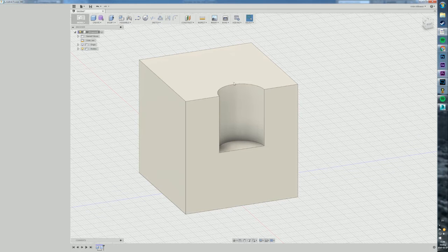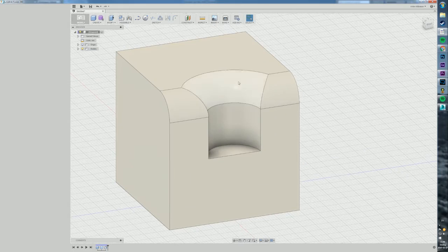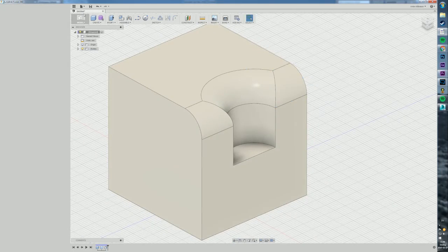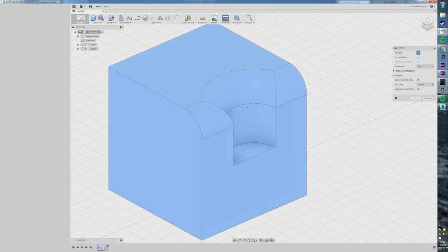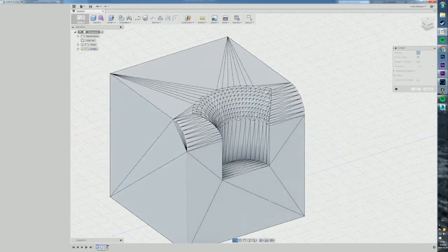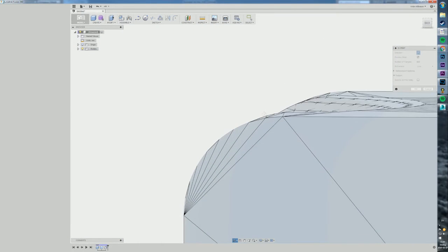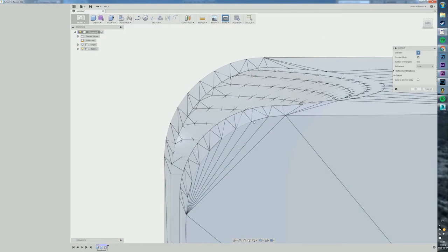So I'm actually going to add just a little bit of detail here to give you a better understanding. Let's do something like that. So these are just chamfers that I defined, but let's go to 3D prints, select object, make sure you have preview mesh on. So I think this is really interesting. You can now see how all of the smooth surfaces are converted into flat triangles. So this edge here is completely flat, this one is flat, and this one is flat. So over all of this model, you actually have steps, almost like the steps of a 3D print.